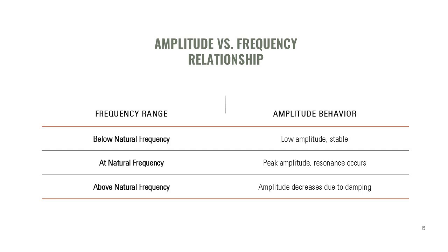This curve helps engineers visualize the critical frequency range and design systems to operate outside resonance zones. By analyzing resonance curves, analysts can predict potential issues and implement corrective actions such as altering stiffness, mass, or adding damping to shift the natural frequency away from operational ranges.